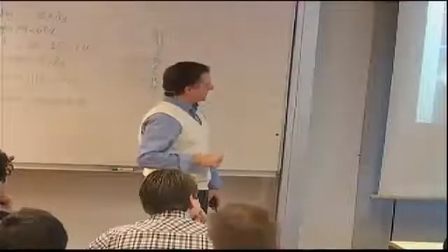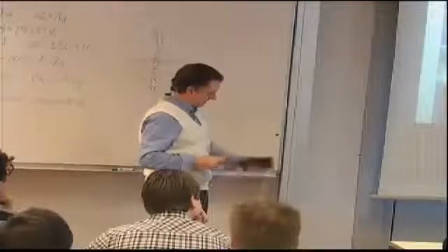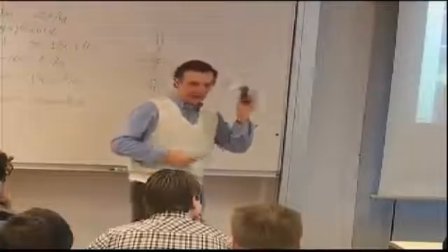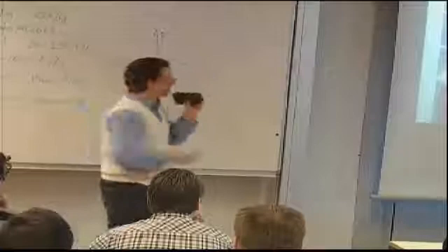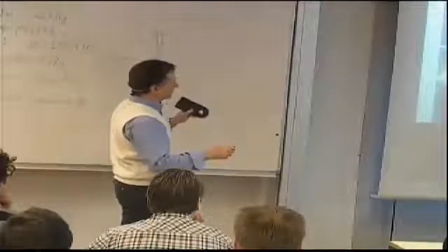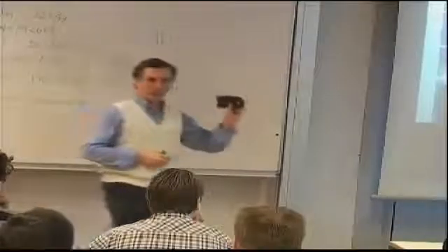And as if all this again were not enough, and it's hard to see here, there's a big delamination, and you will see a similar case on the part that I'm going to pass around. This one was not loaded in the longitudinal direction, it was loaded in the transverse direction. But if you look at it closely, you'll see most of the failure modes.